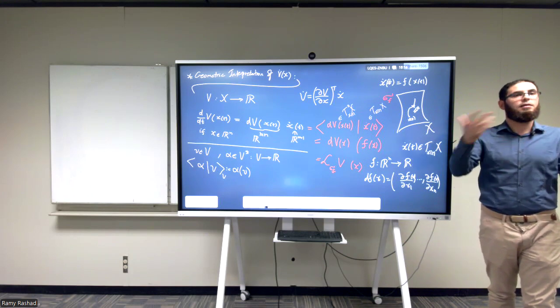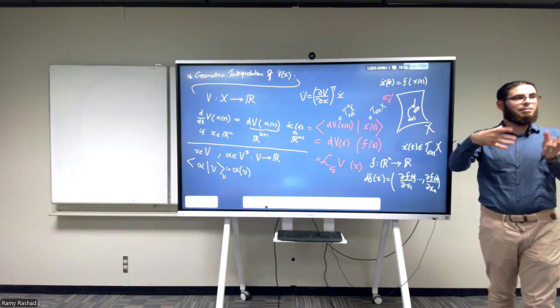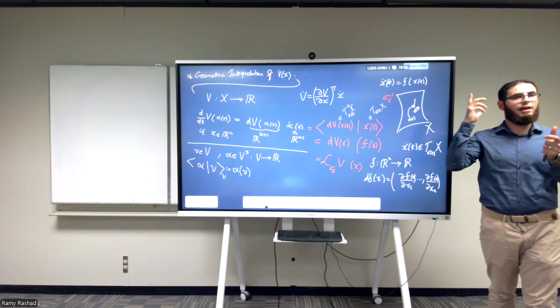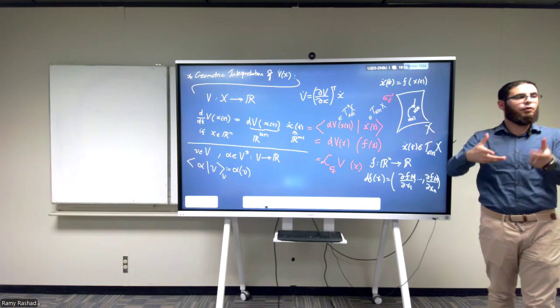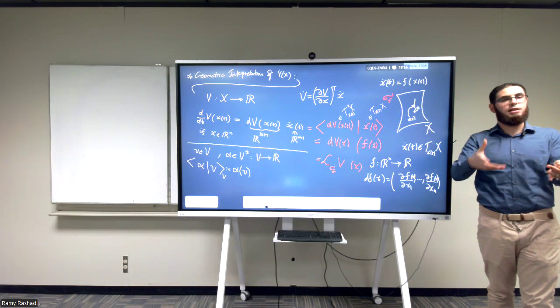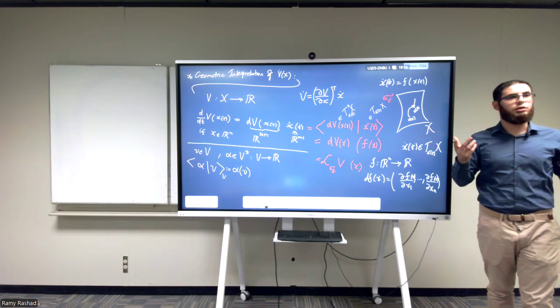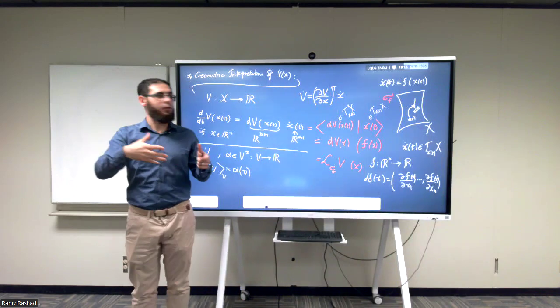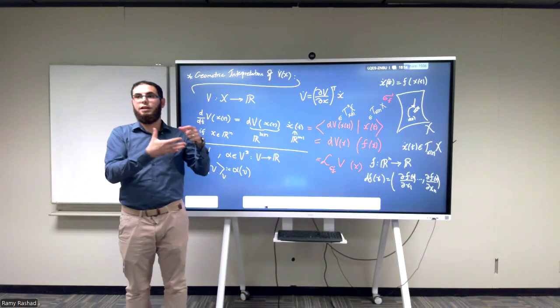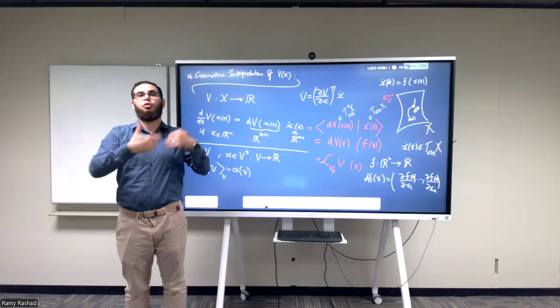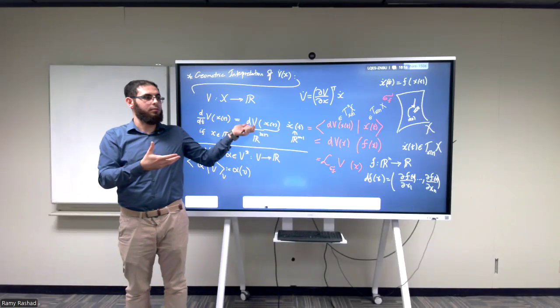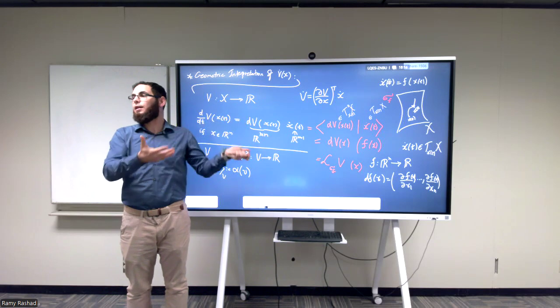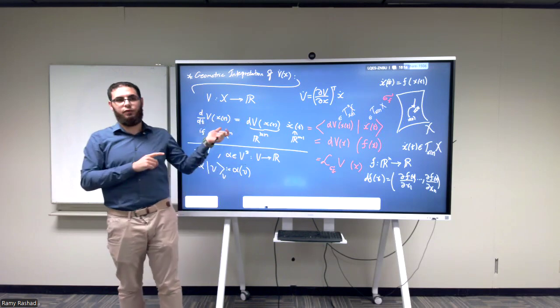And if you have that, you can control any system that lives on SE3. Does anyone have something that lives in SE3 as a manifold in mind? Any actual system? Drones, exactly. So drones have SE3 as their configuration manifold. And if I know how to derive the Lyapunov functions or do Lyapunov-based control on SO3 or SE3, I can design controllers, geometric controllers for drones.